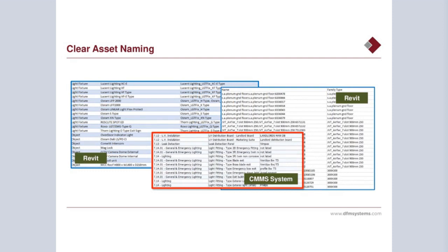Now that really comes into its own in relation to 3D modeling, because the standards used for 3D modeling don't necessarily lend themselves very easily to FM friendly names for items of equipment. They're usually named, as you'll see on the Revit text on the screen, to suit the software rather than to suit the FM needs on the job. But with some guidelines and instructions, it's not a hard job to make sure that there's commonality of asset naming across all of the information sources on a project.